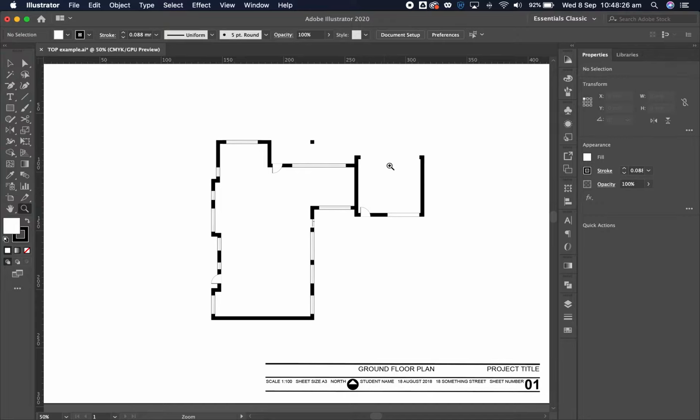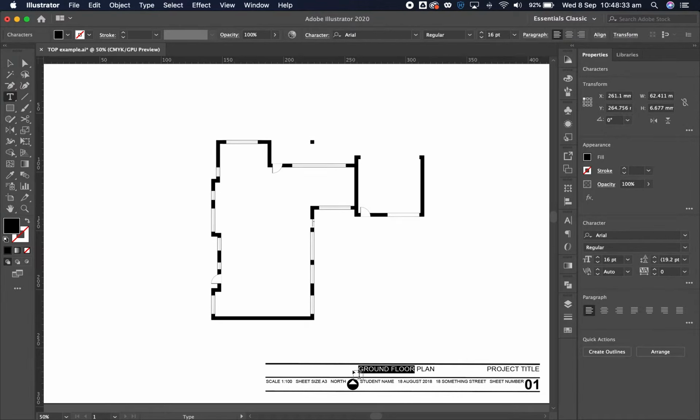Okay, so here we have it. We have our more basic structure. I'm going to also now go over to floor plan and change this over to landscape plan. And we can now also convert this over to 1 to 200 scale, because you'll note that this is an A3 page and we're already at the extent of the A3 page. So we'll convert this over to 1 to 200. I accidentally put in here 120. So 1 to 200 scale, and let's convert this down.